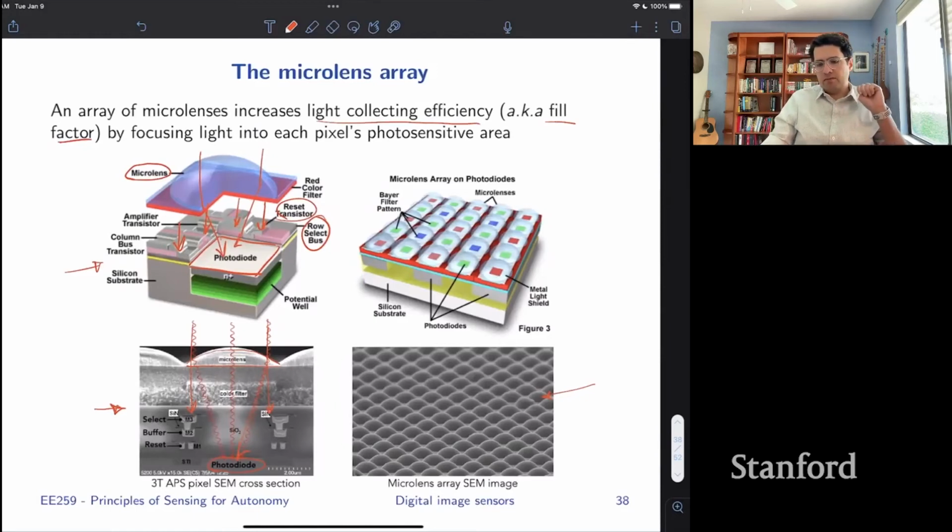Okay, so that's one. The other thing we need to talk about is how do we actually sense color? Because with the architecture we have described so far, every pixel would just measure the total power that's incident on it. And if the semiconductor PIN photodiode, like a silicon PIN photodiode, is sensitive to all the visible light wavelengths, each pixel would measure essentially an average of all colors.